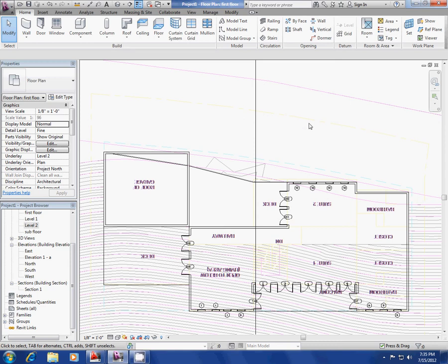This next section, we're going to go over handrails or guardrails, stairs, and roofs. We'll start with stairs. What you'll notice with the stair command is that by default, it'll come with handrails. So it'll develop those at the same slope, say as your 7-Eleven stair. It'll develop that guardrail or handrail just the same. You can delete them afterwards. You could uncheck that. So let's look at doing that.